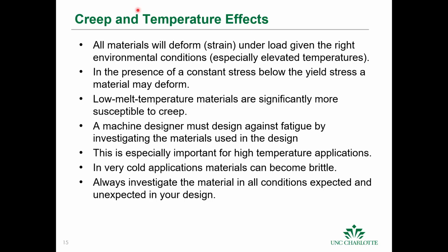Okay, so the point is that things like creep and temperature effects are important, and if you're doing design, you always have to investigate the material in all conditions that you expect, or even conditions that you might not expect in your design. In fact, automobile manufacturers, when they are launching a new vehicle, test them in different environments: Arctic environments, desert environments, and then city environments.